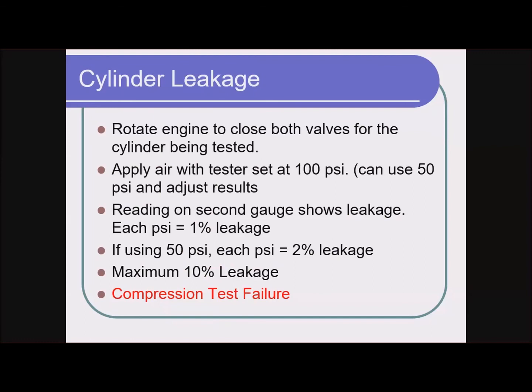If you've done a compression test and all the cylinders tested good, that would be like trying to find the leak on a tire that has good air pressure. If a tire has a leak, how are you going to know? The pressure is going to be low. If a cylinder has a leak, how are you going to know? The pressure is going to be low. So if it passes a compression test, you'd be looking for a leak that's not there. If it fails the compression test, now the question is, okay, we're losing pressure, where's it going?